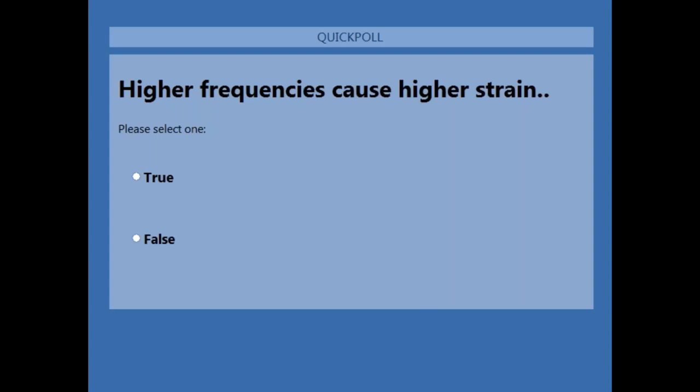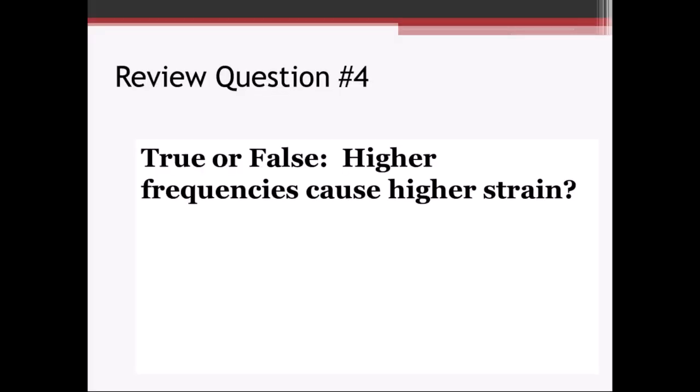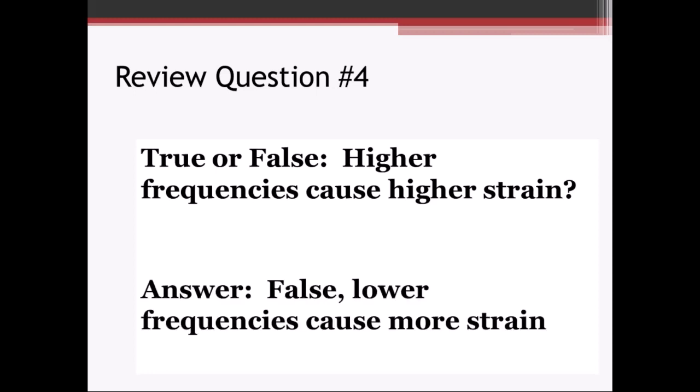Some project specifications require that a contractor hire a vibration specialist like ATL to go out and evaluate the structures: how close is the structure to the work being done, what type of work is being done. Then, based on the information we see out in the field, the equipment that's being used, how close or how far, a vibration specialist can come up with the appropriate threshold values.